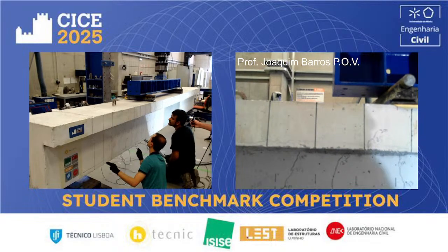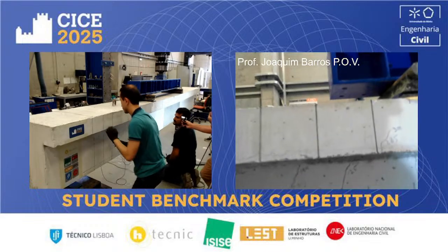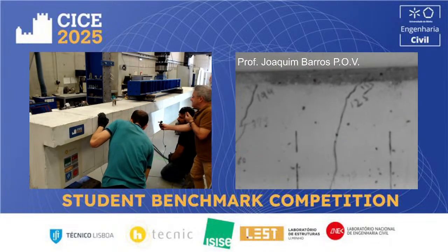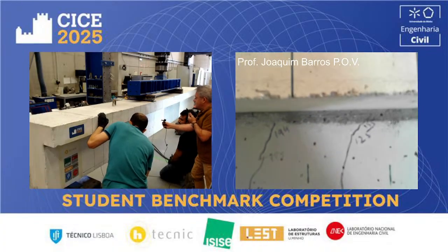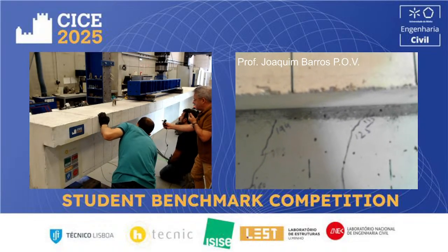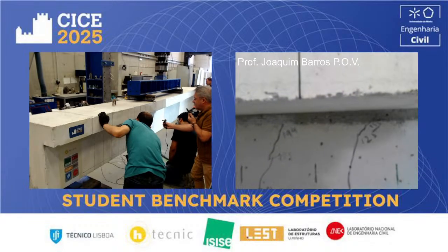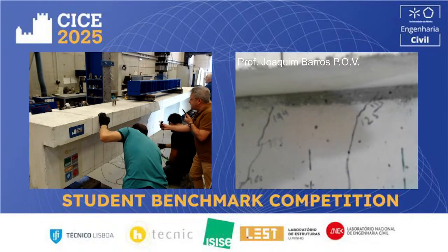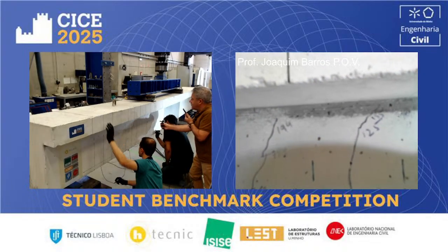The crack closer in the shear span, but closer to the loaded section, so we can see that the crack width almost in the center of the web is already significant, so maybe 0.2 to 0.3 millimeters.